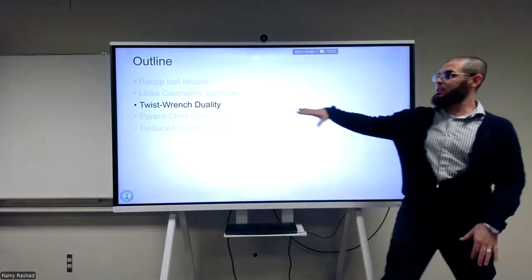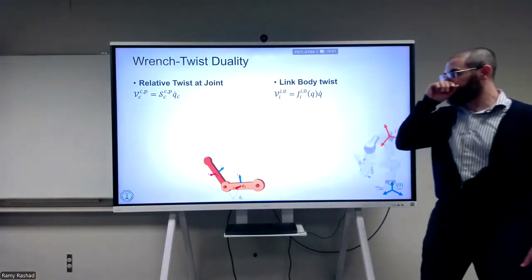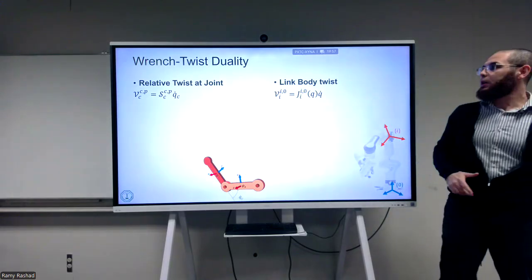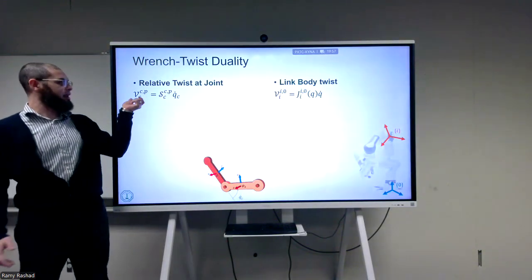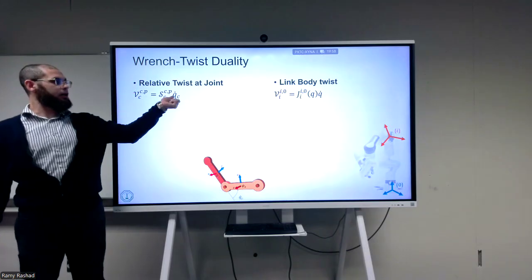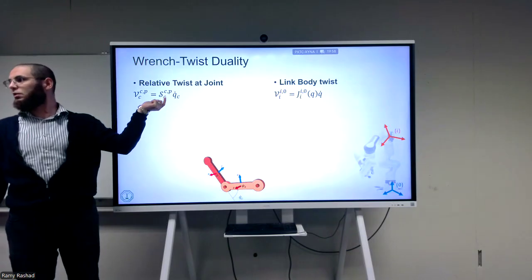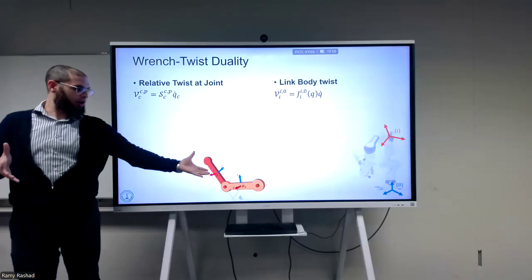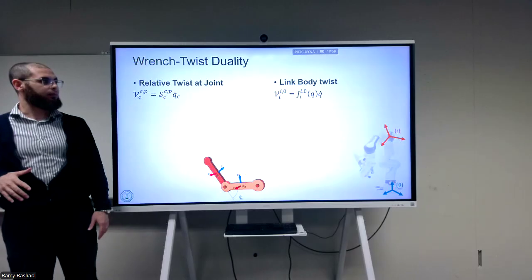Okay, so this is the first piece that we looked at, the ith link Jacobian. Now let's look at something very important. So these are the two equations we discussed so far. And we said that when we have a joint connecting two bodies, a parent and a child, the relative twist will be given by q dot multiplied by the 6 by 1 vector, which we call the screw axis. This is a constant that defines, in the end, what axis we are rotating around and the distance of how it's placed in the child and parent.